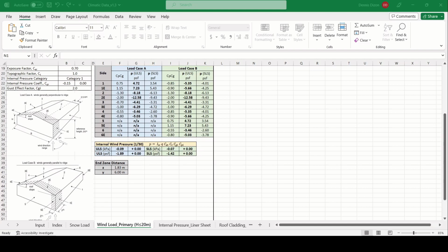For example, if it's a flat roof, like I said earlier, the internal pressure is this way, and then it will cancel out. And then what happens with the external pressure is this is upward, but we are only calculating for the lateral. So that's why this is not included in the lateral analysis.